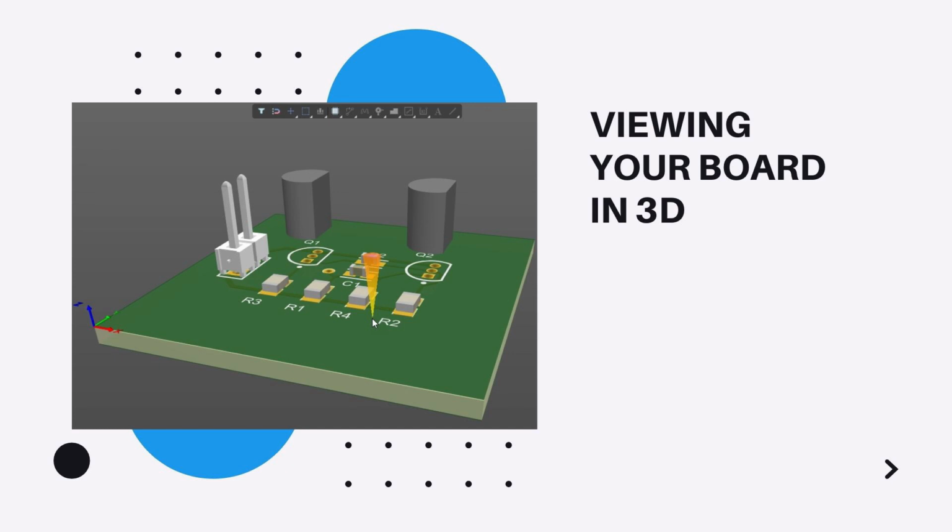In rotation, shift, right-click, hold and drag. Note that when you press shift, a directional spear appears at the current cursor position. As shown in this image, rotational movement of the model is made about the center of the spear. Now position the cursor before pressing shift to position the spear.